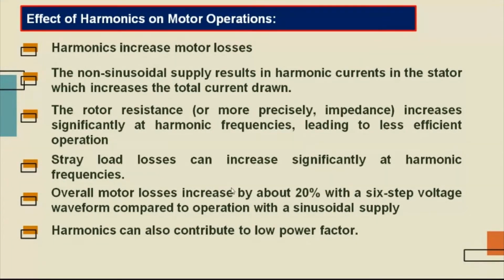Harmonics can also contribute to low power factor. In the previous lectures, we have already seen how low power factor contributes to the increase in demand charges, and how the increase in demand charges will affect the overall electricity bill of that particular consumer. So I will not go into detail right now.